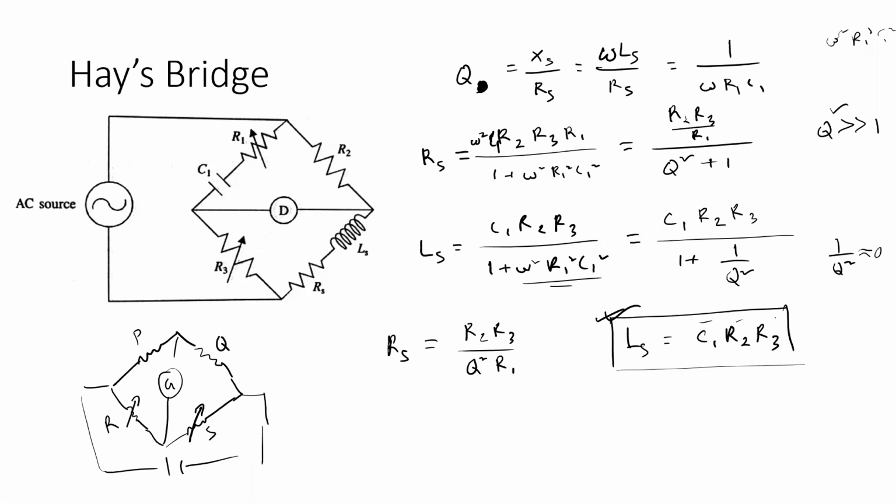So similarly here as well, as these are dependent on multiple variables, there will be some problem in tuning them, especially when the inductor or capacitor has a low quality factor and the resistive part is dominating, because the effect of both these resistances, R1 and R3, is on Rs.